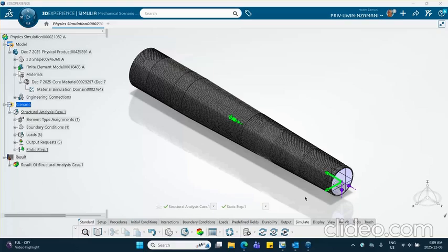We're going to do the nonlinear geometric effect and nonlinear material simultaneously. The only thing that I have to do is go to the previous model that I created in tutorial 7, which dealt with material nonlinearity only, and activate a switch.